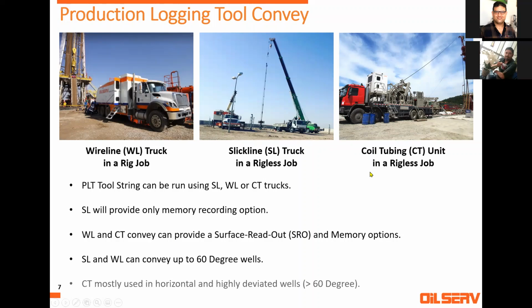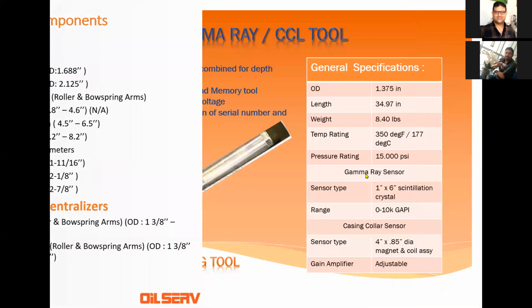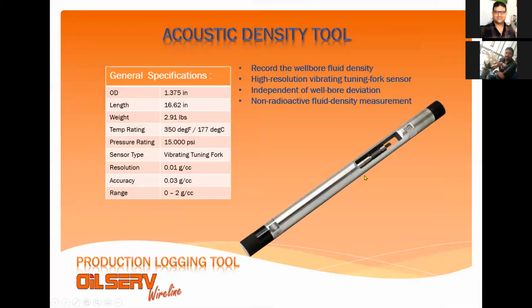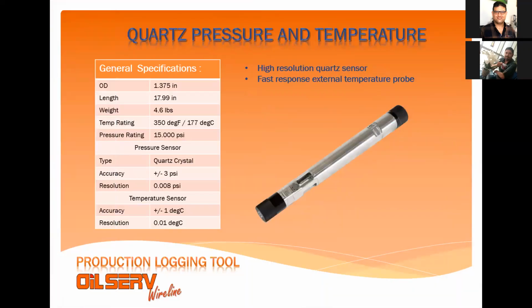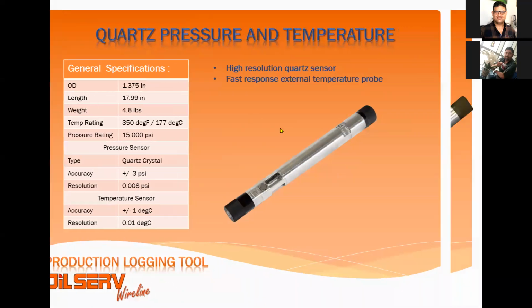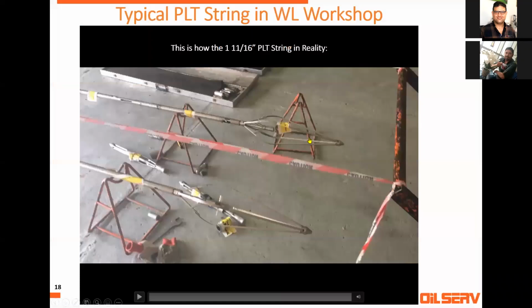But usually in the field, you always keep the flow. You don't want to lose money, especially for a producer, and even for an injector. But you shut in the well if you want to make a pressure buildup, or shut in and run a pressure falloff. As you will see, I put some examples for shutting in the well. Excellent, thank you for the question. Really good one.